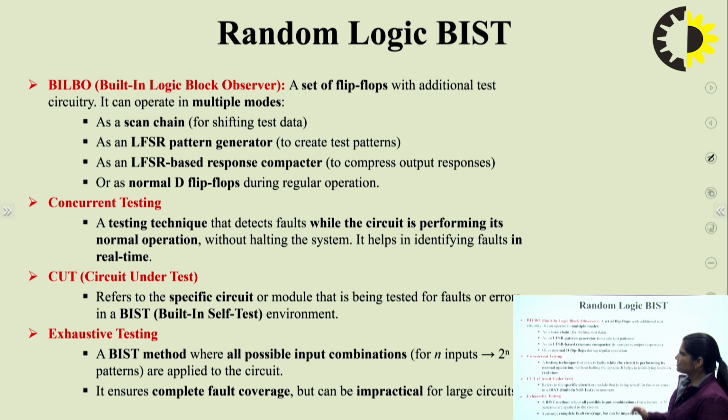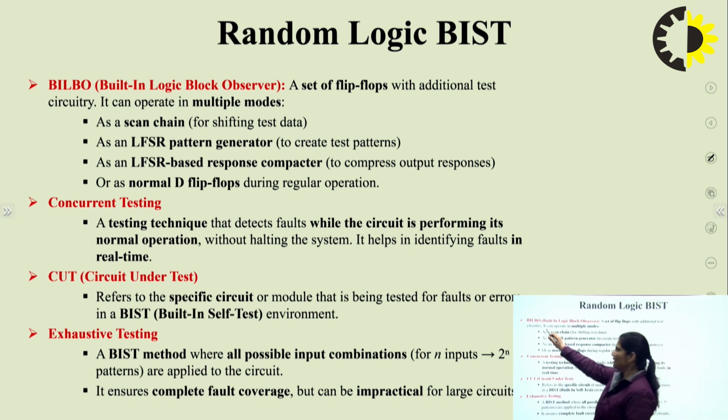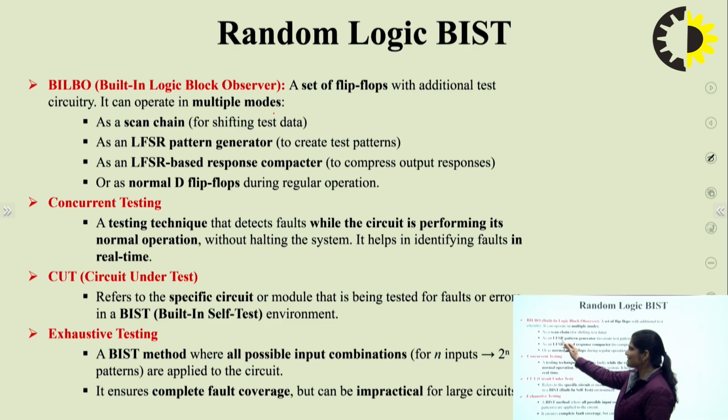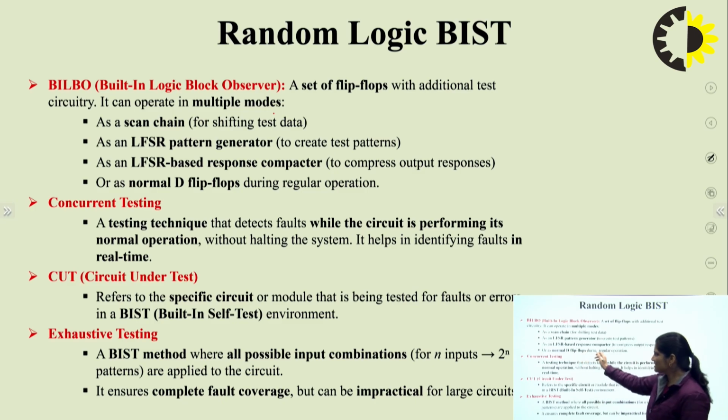Now, here BILBO, so this is random logic based. Built-in logic block observer is a set of flip-flops with additional test circuitry. It is operated in multiple modes: as a scan chain, as a linear feedback shift register pattern generator, as a linear feedback shift register based response comparator, or as a normal D flip-flop during regular operation.